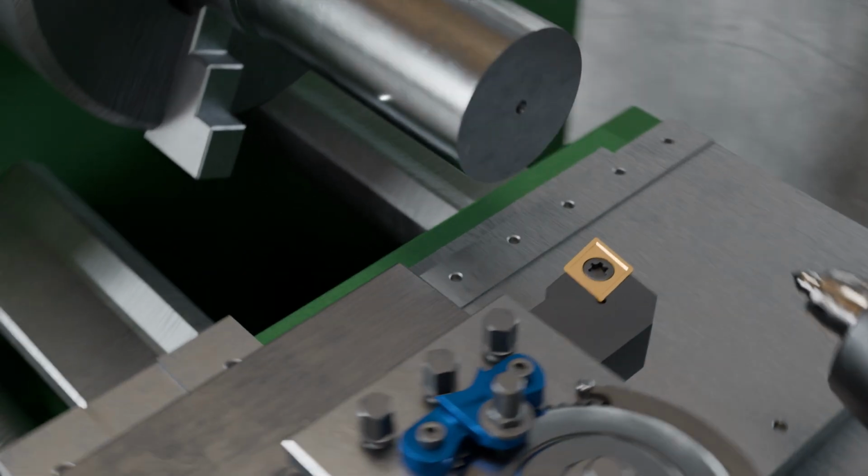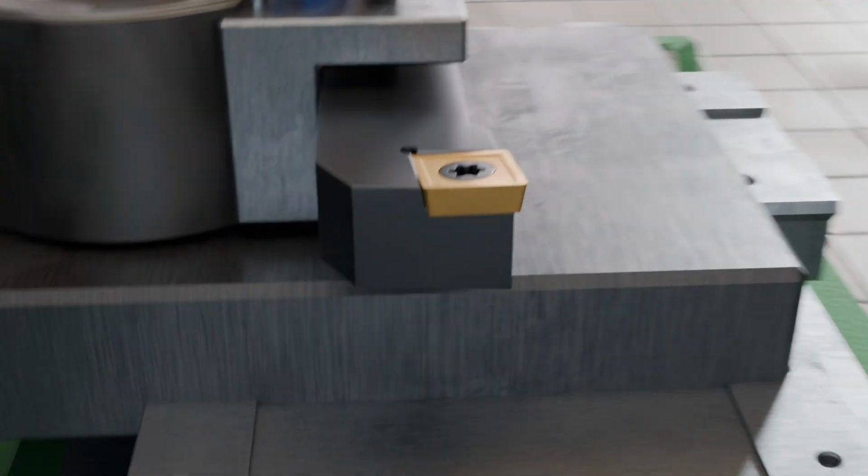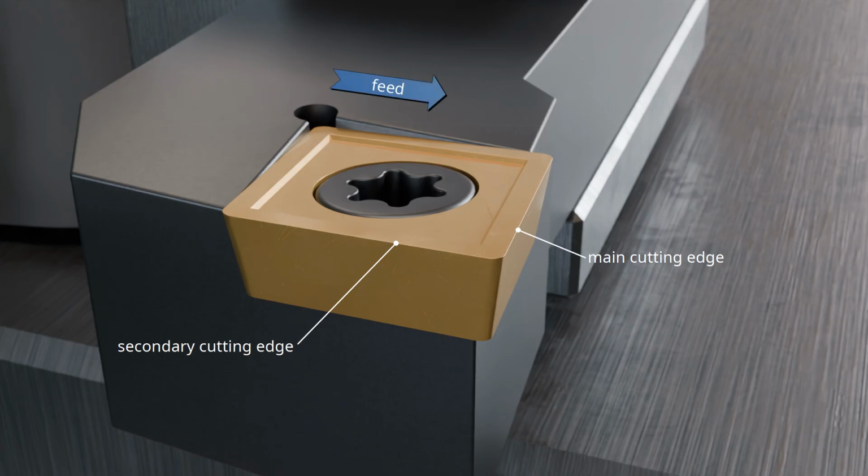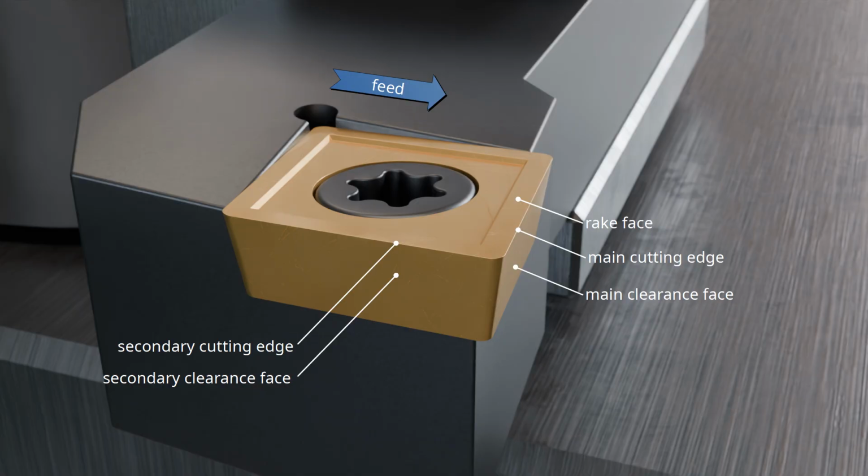Let us take a closer look at the geometry of a turning tool with an indexable insert. Depending on the feed direction, the cutting edge of the insert has a main cutting edge and a secondary cutting edge. The main cutting edge performs the primary cutting action and is oriented in the feed direction. Accordingly, there is also a main clearance face and a secondary clearance face. The rake face is the same in all cutting cases.